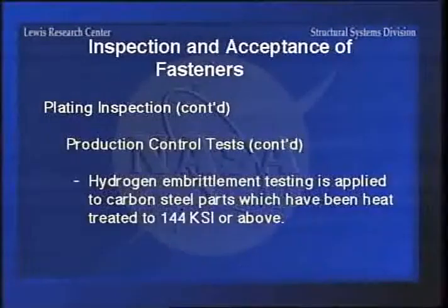Now, hydrogen embrittlement testing, there are different schools of thought on where you should start on the hydrogen embrittlement testing. Some of the fastener manufacturers of the lower strength fasteners say, gee, you don't have to do it on lower strength fasteners because you can't get hydrogen embrittlement. Well, a guy by the name of Lou Raymond, who is kind of the guru in the U.S. on hydrogen embrittlement, ran some tests and decided that you get hydrogen embrittlement all the way down to about a grade 5 fastener. The only thing is it takes it longer to show up.